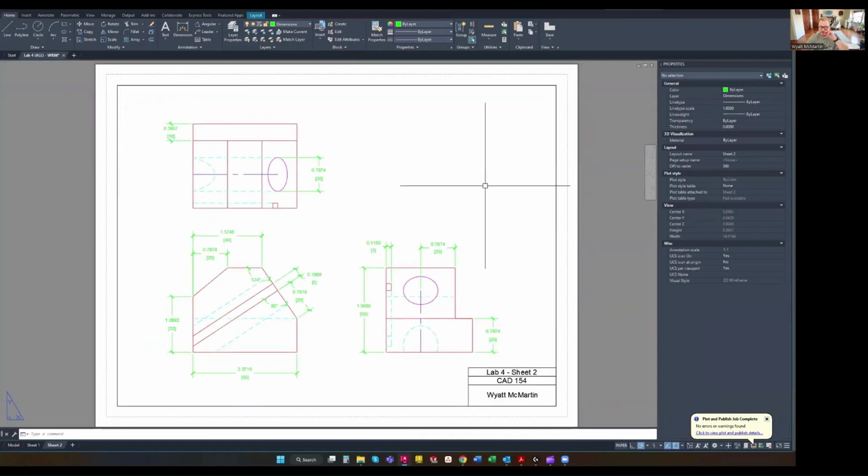Just to show you that with it zoomed out, I'm in the viewport right now. You can see that it's bolded, and then I'm going to type PS, enter, and that's going to get me out of the viewport. So that is one nice thing to know. I'll tell you that because I had an issue. I always used to have an issue with viewports until I understood them fully. So, very powerful tool, but it can be a little bit frustrating and finicky.